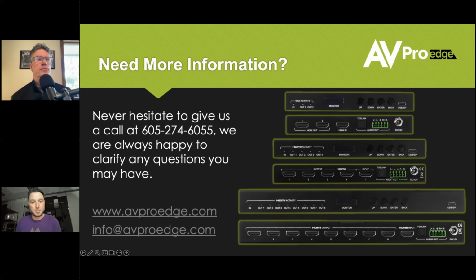James had a follow-up question about the 2-channel thing. He says, will that affect the audio format in the surround zone by changing the EDID? Yes. It doesn't downmix, right? You can only pull out 2-channel audio over analog or Toslink. Correct. And if that's the case, we do have ADMs for audio downmixing. Yeah, use the AVDM. You'd want to make sure you bought the DA that had an extra output, and you would plug that ADM into that extra output at that point in time.